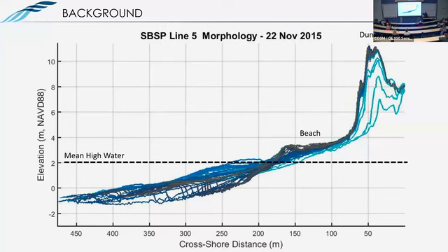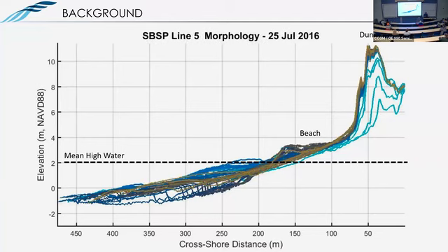So in many places where we have topographic data over long timescales, it's really quite common to see dunes growing because there's more inputs from wind-driven sediment transport than losses via wave-driven sediment transport. If this wasn't the case, dunes would not likely naturally persist in these locations. So at least over timescales of relevance that we care about, years, decades, dunes are really common features.